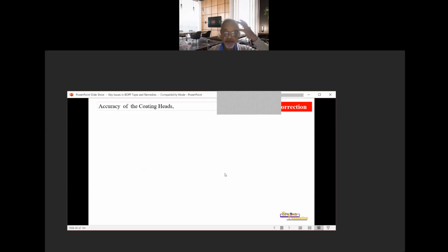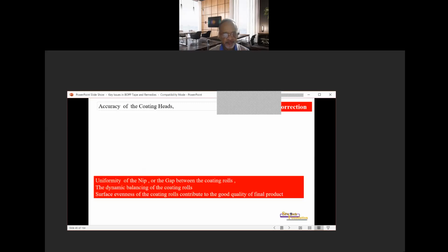Good morning, friends. To continue our lecture on the key issues in BOPP tape manufacture, the remedies, let us continue part 2. Accuracy of coating heads. Uniformity of the nip or the gap between the coating rolls. The dynamic balancing of the coating rolls. Surface evenness of the coating rolls contribute to the good quality of the final product.